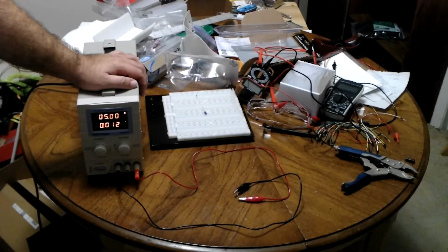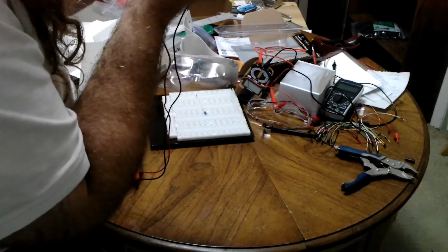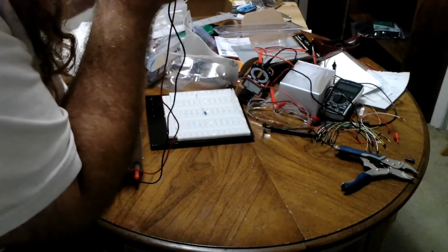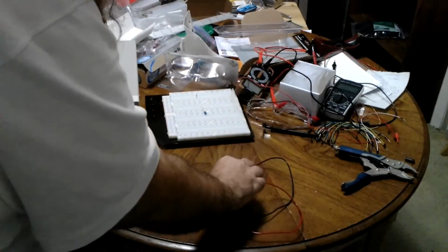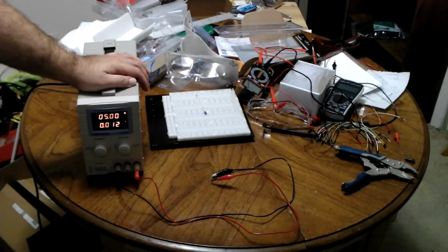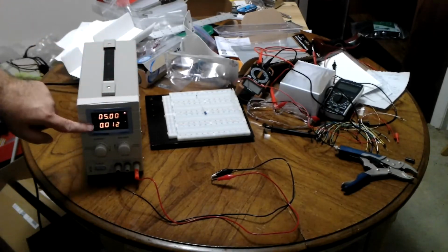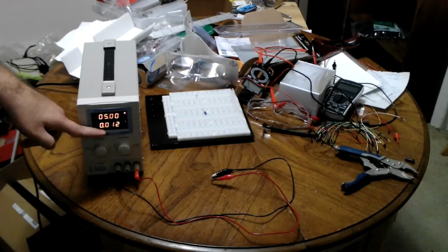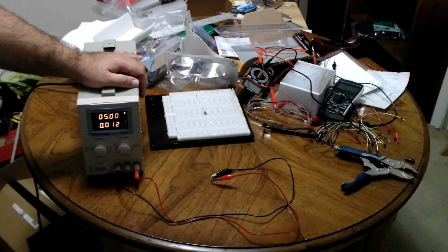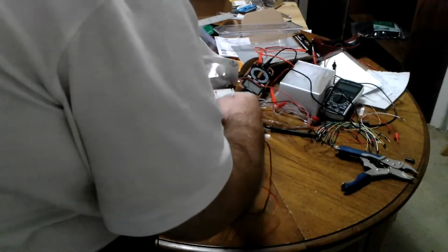So, did you see that little puff of smoke? That was your resistor dying. And now you'll see, I can smell it, but you don't see much wrong with this resistor. Every component fails in its own way. Some of them tend to go loudly and some of them quietly. But you will see that now it is limiting the current to 12 milliamps because the resistor is no longer effectively resisting.